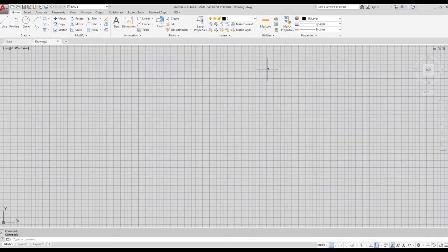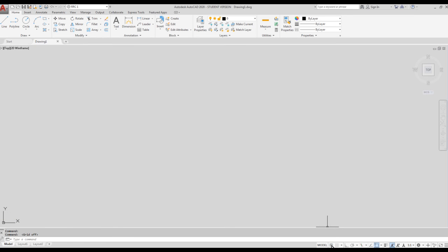Each drawing editor, or each sheet in the drawing editor, starts off by displaying a grid. The grid system is useful depending on the industry that AutoCAD is being used with. The grid itself can be turned on and off. There are two ways of doing that. The first way is, if we take a look at the very bottom right-hand side to the buttons shown, there is one button right next to the word Model. When I click on that button, it turns the grid off. If I click on it again, it turns it back on.